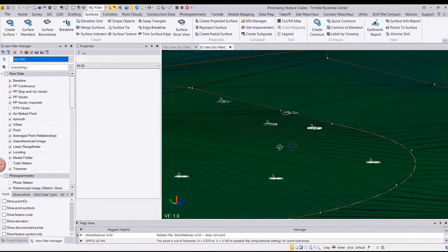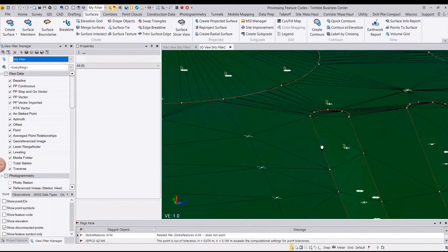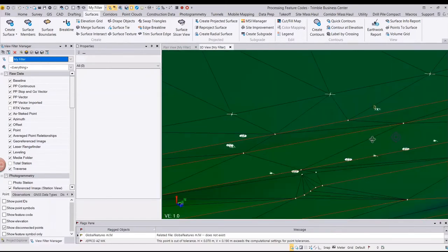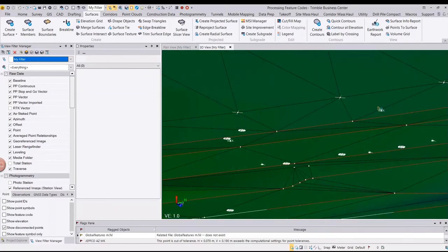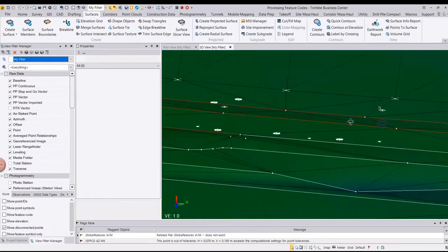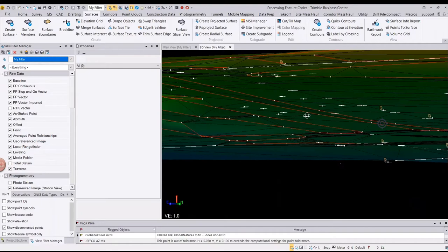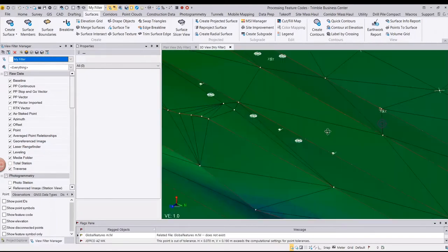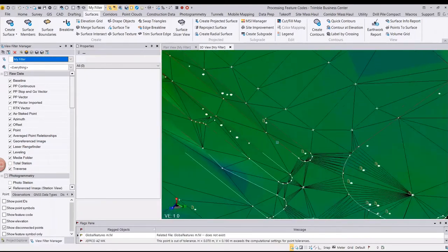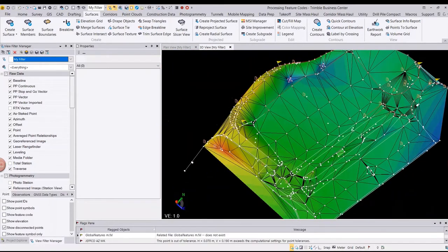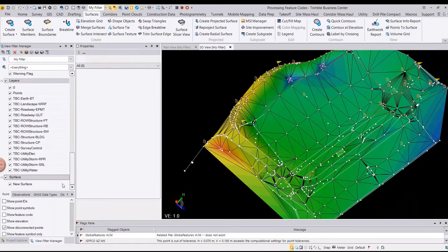Oh, this tree is kind of sitting on the floor, but maybe we can look at this light pole. As you can see, when we surveyed this pole, we probably hit the top of that pole. So now when we create a surface to represent the natural ground, this sign pole will not pollute our natural ground. Okay.